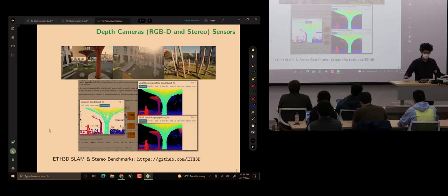For the stereo camera, we usually have left and right images, and we come up with an algorithm to recover depth value of a pixel. It's a topic in computer vision, how to recover the depth, but if you see a scene from two different views, and if you know the relative transformation between camera lenses, in this case, just the baseline, then we can recover the depth. It can be noisy in practice.